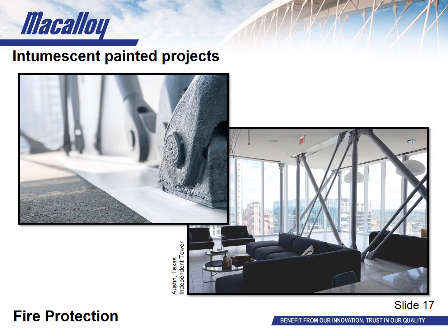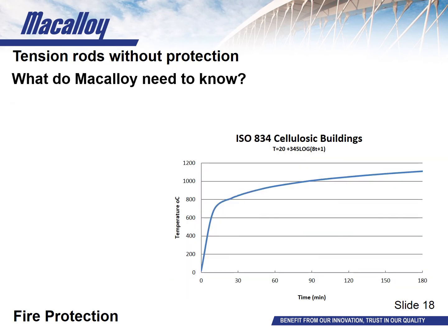So they've done a really good job at blending that in and complementing the building fantastically for that bracing structure. Although at Macalloy we cannot advise on the appropriate coating to suit the fire rating required, we can, based on 1993 Part 1-2, advise on which size tension rod would be suitable when left untreated.